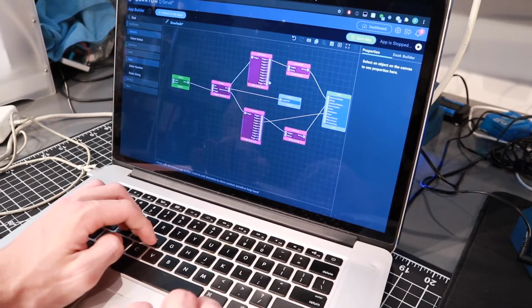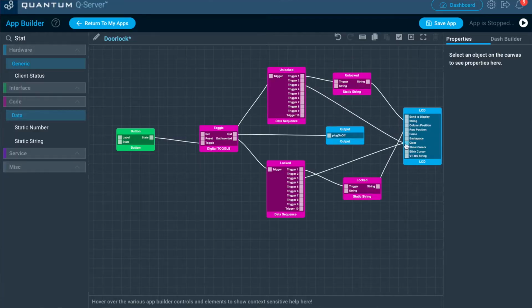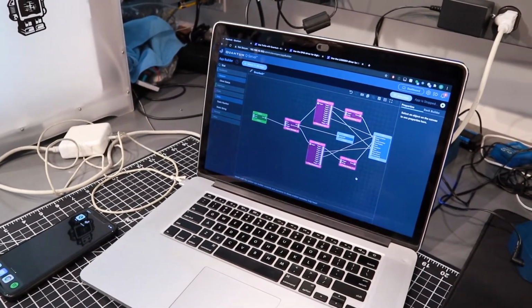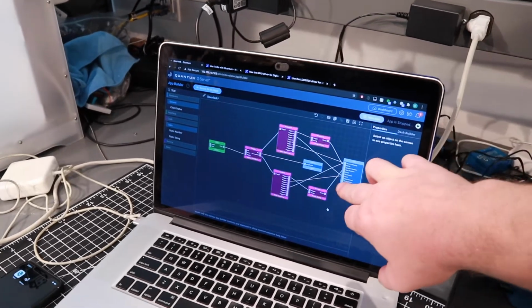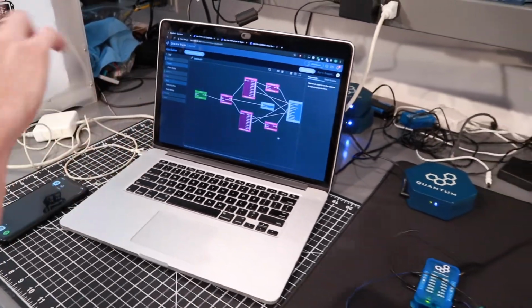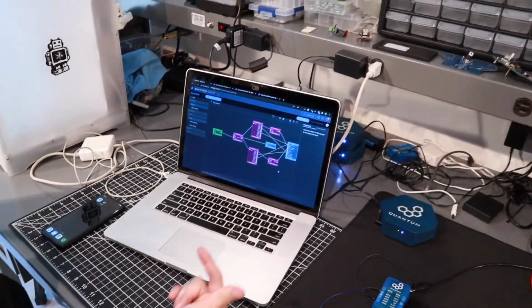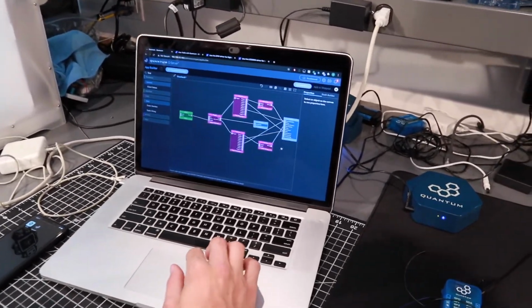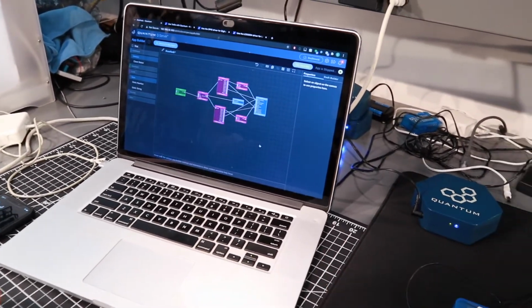And then we'll clear the LCD every single time one of these is activated. So we're going to clear the previous message off of the LCD so that a new message can be written onto it. And then the string has already been sent to the string block in both of these sequences. So now the next step in the sequence is to send that message to the LCD display. Oh, okay. So it's actually sending the message to the LCD first, and keeping that in the object. Right. Then we clear it, and then we actually send it to the display. And you could swap the sequence as well. You could initially clear the LCD, then send the string, but it has the same effect. Right. And so now we'll have a message displayed on the LCD.